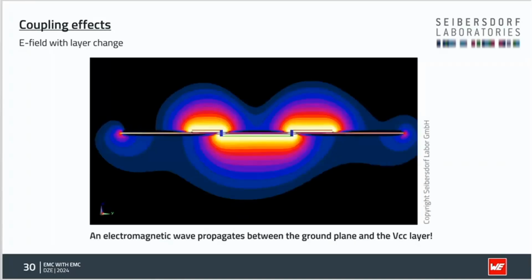So, of course, we cannot avoid vias. I mean, we can certainly not avoid them with 2 layers, nor 4 layers, nor 6 layers. But what we can do is, if we have a signal that's traveling really fast on a transmission line, we should avoid vias at all costs. And then we go to the analog part or the slower digital circuitry and place them there if needed, and only if they are needed.